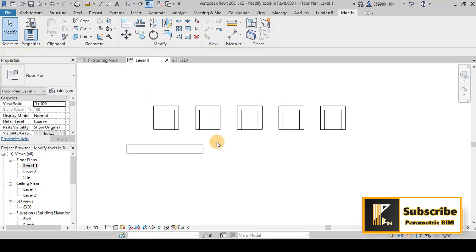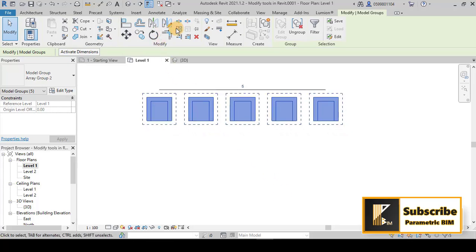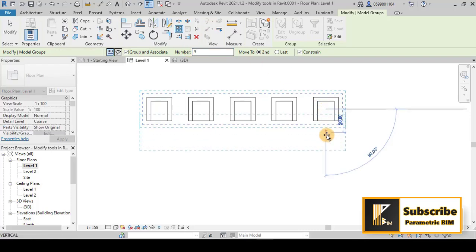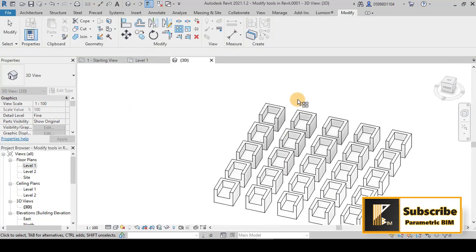So now if I want to make an array in the vertical side, I will do the same thing. So maybe I put 5 here. I will go to the center line, and then the distance between the center lines is 150 centimeter, and then it will be ready as you see here in the 3D.